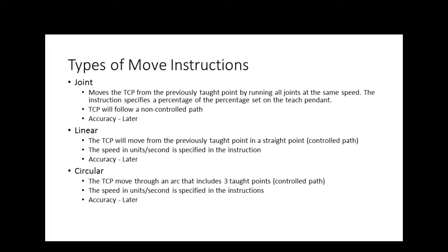A lot of people ask which is the fastest. We say a linear move is a straight line and a joint move is not. Most people say it's a linear move because it's a straight line and the shortest distance between 2 points. And I say, okay, so that means I can go from here to Birmingham on the highway up here where they turn all the red lights green and I do 100 miles an hour. Or I get on the interstate over here and I'm limited to 30 miles an hour. One of them is pretty close to a straight line. The other one, we're going through all these cities and it's got curves and everything. It's not a straight line. So you can't say the fastest speed is the straight line.